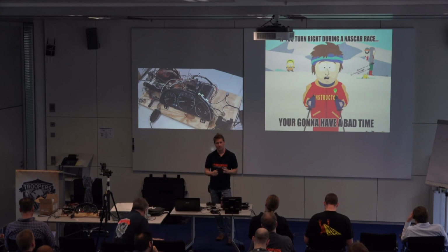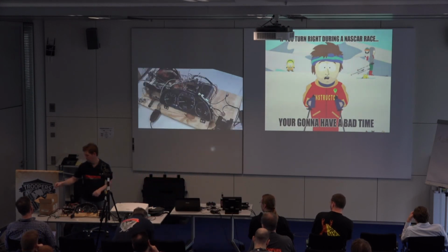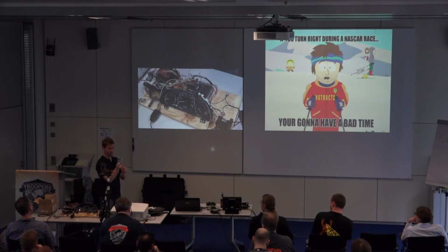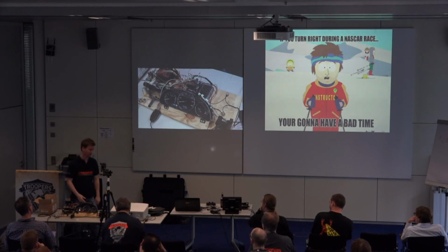There are some proprietary modes and PIDs for certain makes and manufacturers, and you can maybe get those through brute forcing. I don't know how well that would work for you. Typically the method is to get a dealership tool and use a Y connector. I have one here, still in its packaging. It plugs in and splits off into two pigtails, then you put a sniffer on one end, plug their tool into the other, and record.